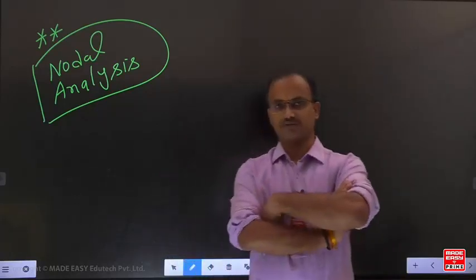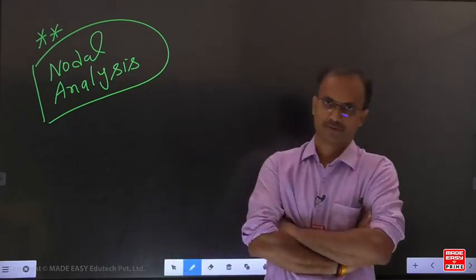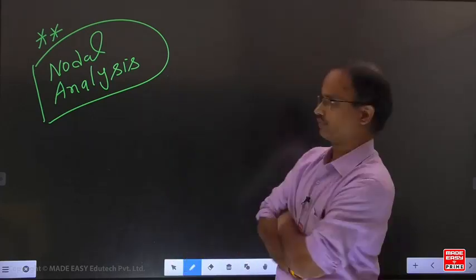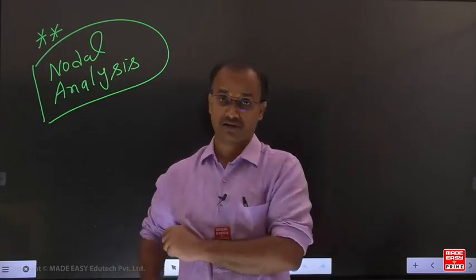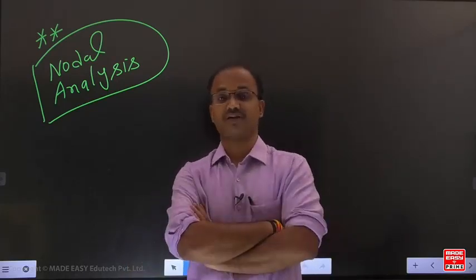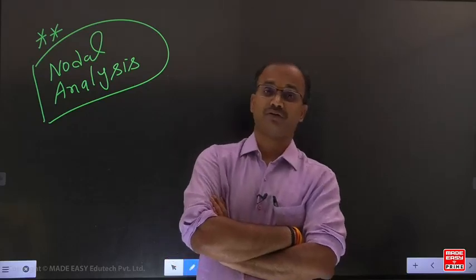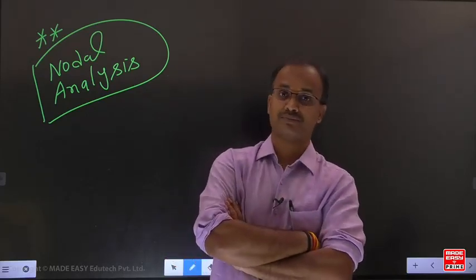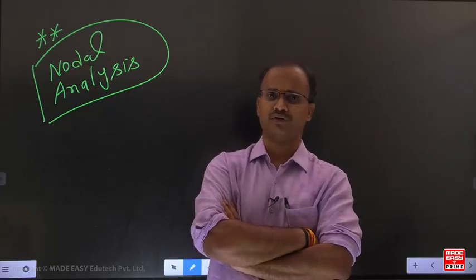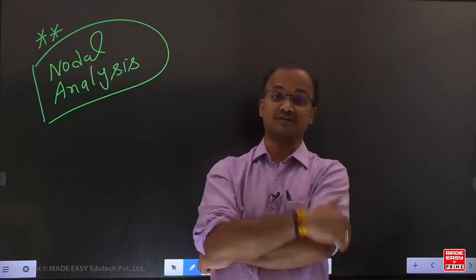See, so far we discussed mesh analysis. Mesh analysis is valid only for planar networks. But nodal analysis is valid for planar as well as non-planar networks. And one more thing: in the further chapters, steady state AC circuits, theorems, transients, two-port networks, for many questions, with the help of nodal analysis we can easily find the answers.